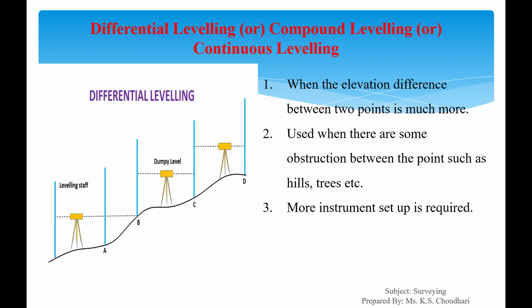Now the differential leveling. Look at the diagram. Okay. When the elevation difference between 2 points is large, differential leveling is used. It is used when there are some obstructions between the points such as hills, trees, etc. In this leveling, more instrument setups are required.